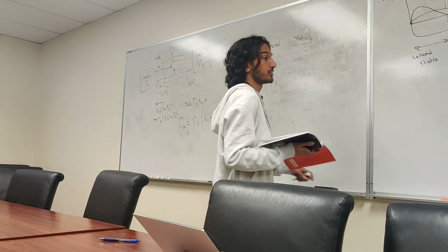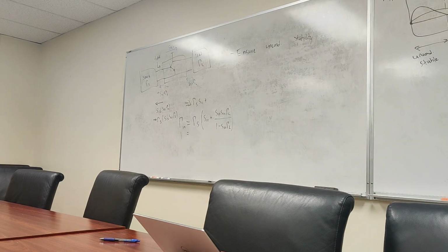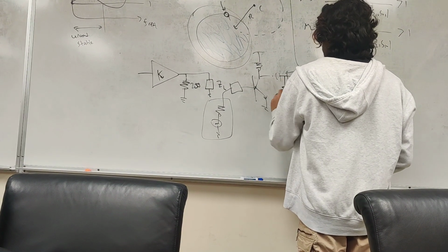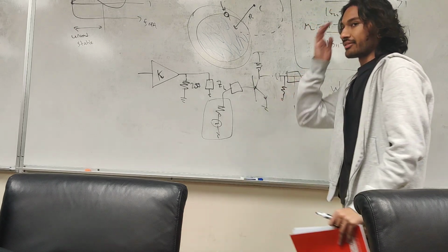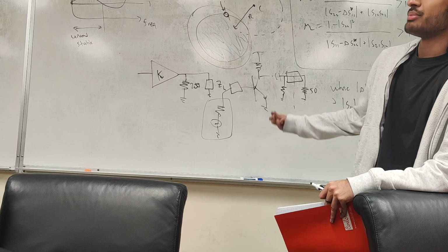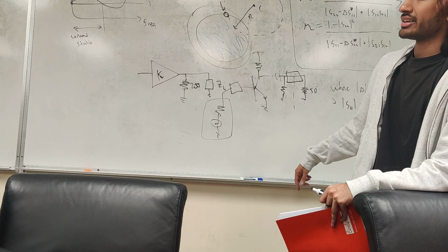Because what we saw from over here is it's a 200 ohm resistor, right? Where it was before over here, right? Or just going to put it here too. All right. What this does is it changes the biasing of our transistor. You have S parameters given a certain biasing, right? But if you change the biasing, your S parameters change.